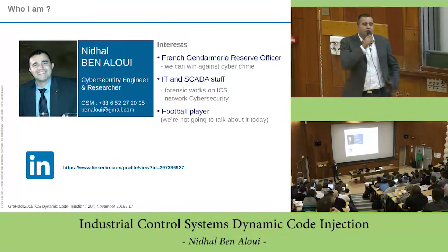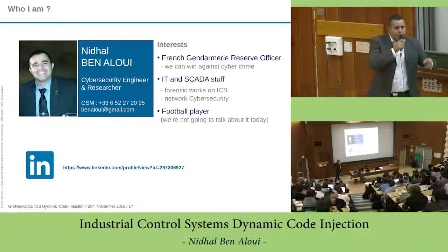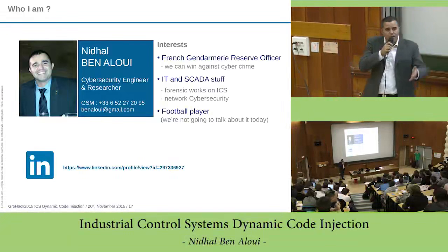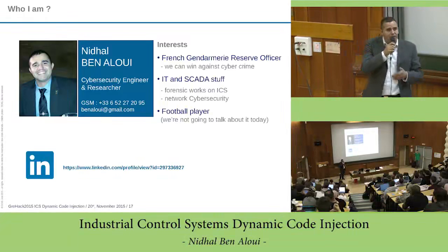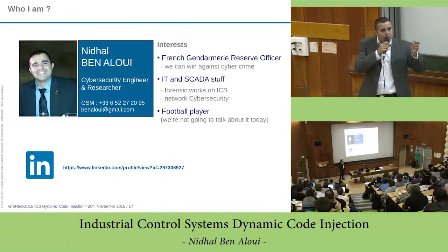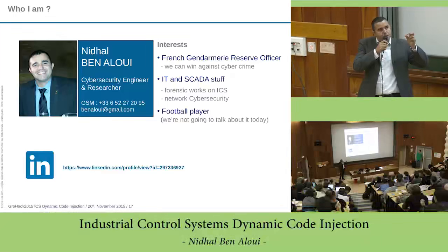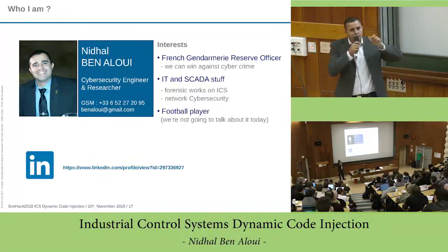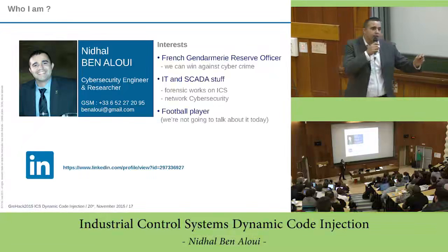Exactly, that's what we're doing. In the probe, I can show you an example with Suricata, and I can also give you an example of a rule after the presentation. In the rule, for example, we say the second rack, at offset 24, I should have this value. If you have this value, that means it is a code injection through the PLC.